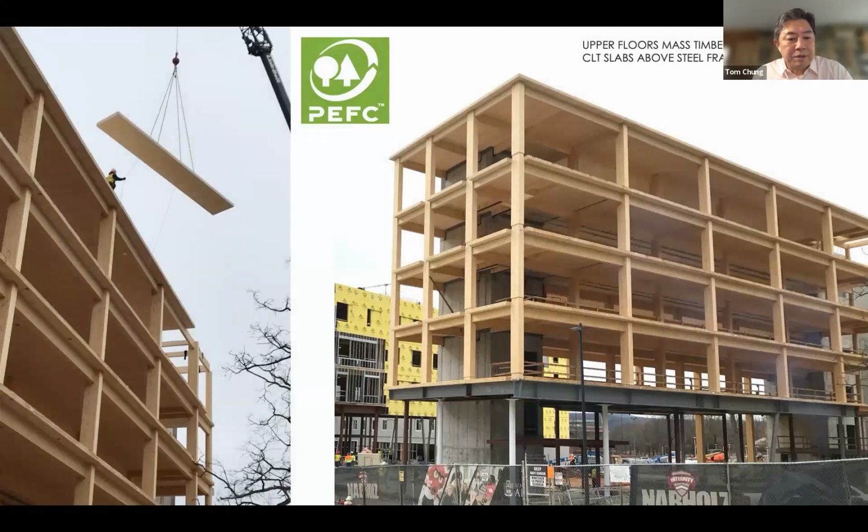So here's an image of the building under construction. You can see the upper floors where the student dorm rooms will be, the mass timber structure of glulam columns and beams and CLT floors. And in contrast, the openness of the ground floor. Here we're using steel beams to create those openings, those transfer beams, those cantilevers, because steel, in terms of being able to do those elements, is much more efficient than wood. But wood, given its strength to weight ratio, is much stronger than steel or concrete, possesses those advantages and allows us to make these highly regular, highly modular areas of a project much more efficiently, much more cost effectively.